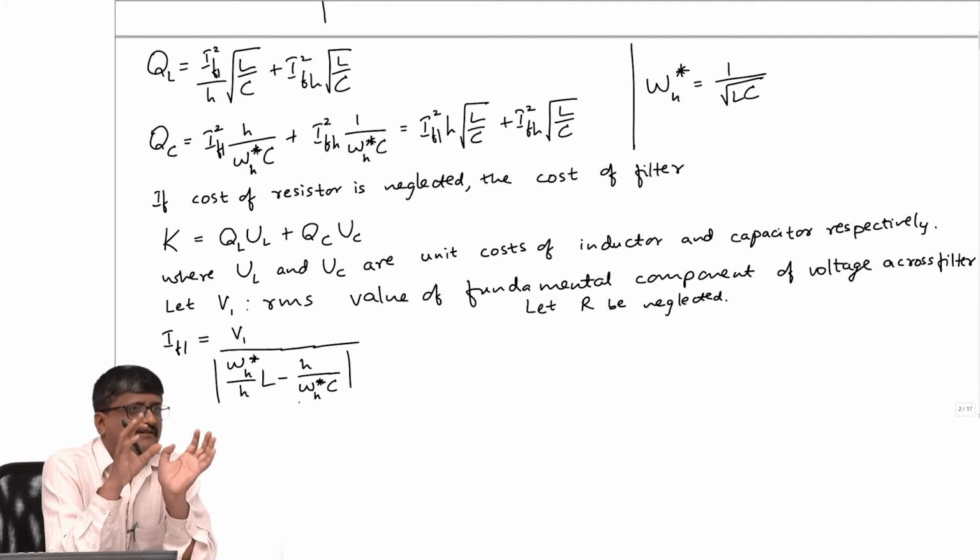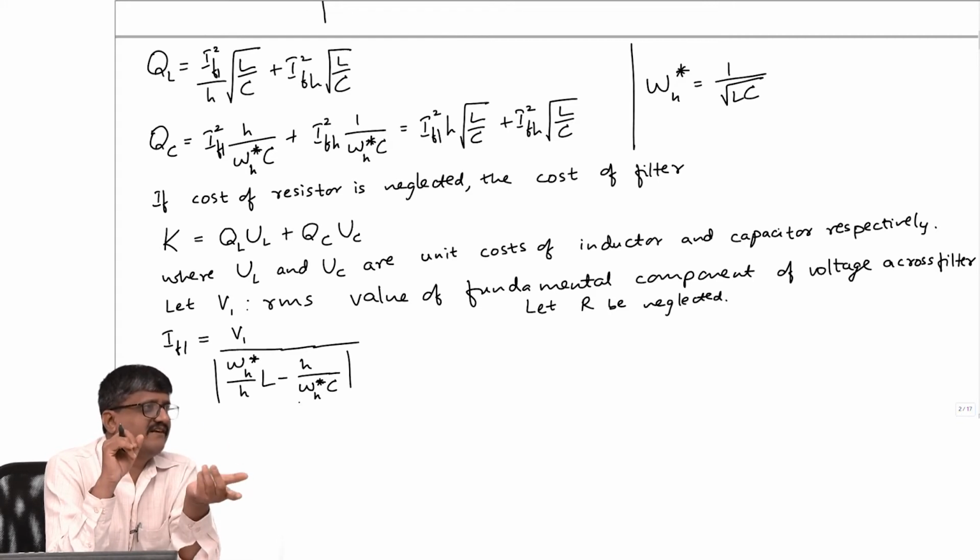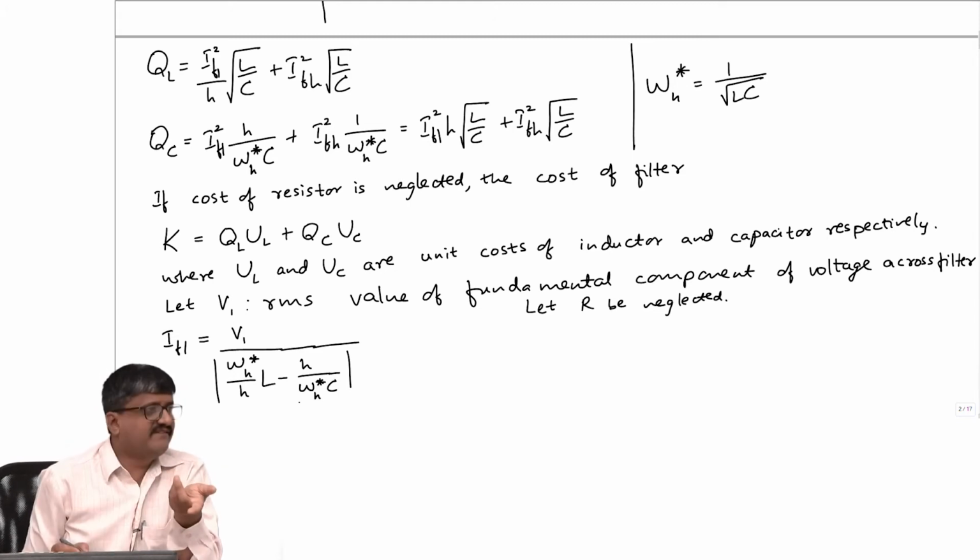I will repeat. Now the capacitor and inductor will have the same reactance at resonant frequency. Fundamental frequency is lower than resonant frequency. So capacitive reactance will be larger. So I don't need this modulus. I know which one is larger.